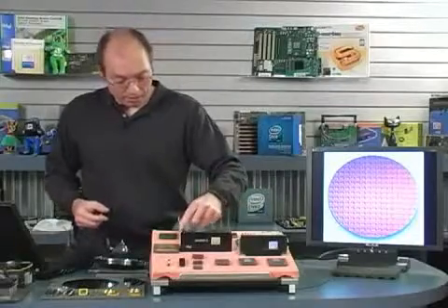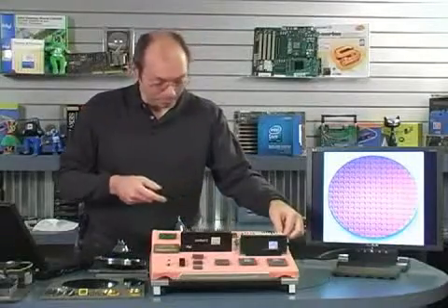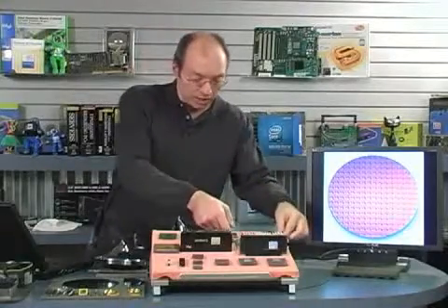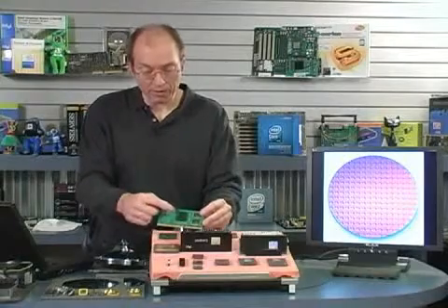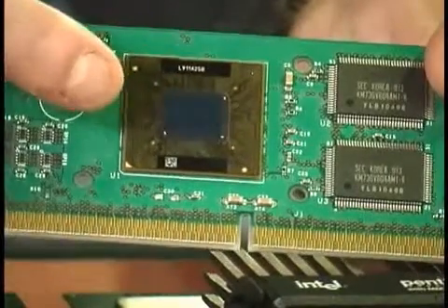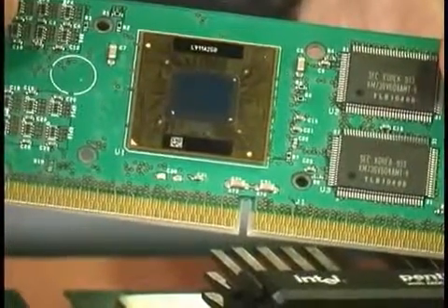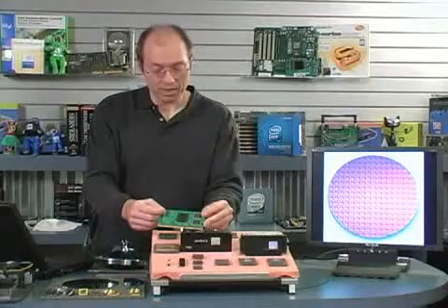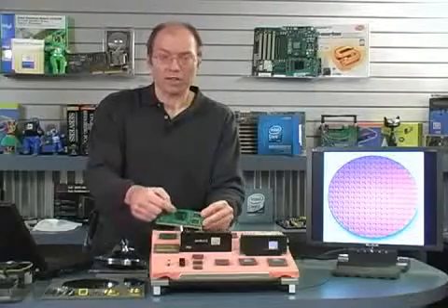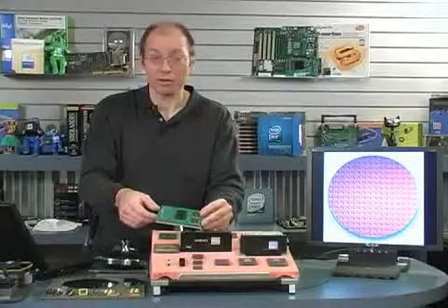Now, continuing this evolution, talking about processor packaging, most of the time when a processor is made, you don't actually see the die. It's covered up. Well, some chips were made where you did see the die. I showed you this Pentium 3, and you can actually see the raw silicon die on top of this chip. That's the actual silicon base of the processor. It is flipped upside down, so the circuits themselves are not visible, but still, that's the raw silicon die. There was a problem with this design: when you attached a heatsink to it, it's basically perched on this little pedestal of silicon, and if you put too much pressure to one side or the other, you could crack it.